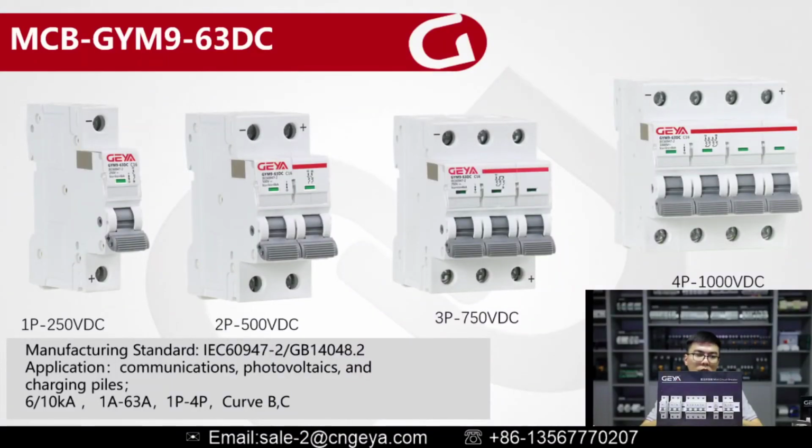Its breaking capacity can do 6 or 10 kiloamperes. It is the same as the AC circuit breaker. Rated current from 1 ampere to 63 amperes, and the pole number from single pole to 4 poles. This one also can do curve B and C. Here I have to note the AC circuit breaker GYM9 can do curve B, C, D, but this model GYM9 63 DC can only do curve B and C.